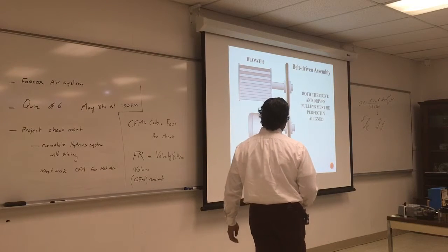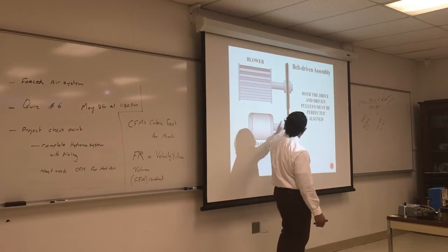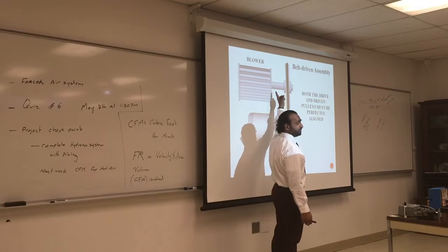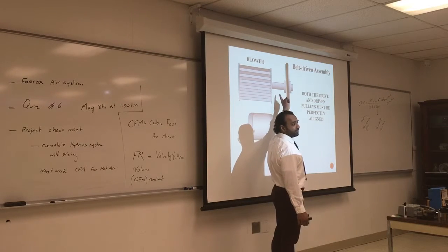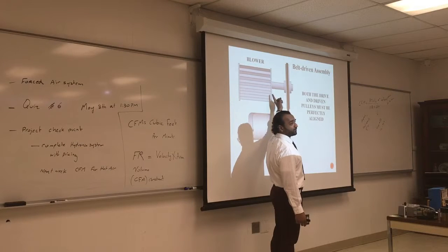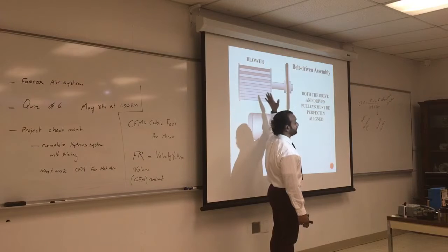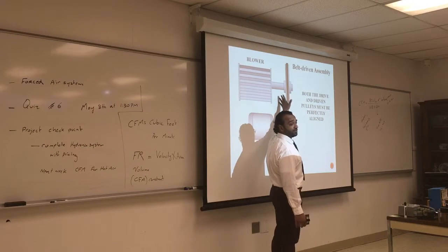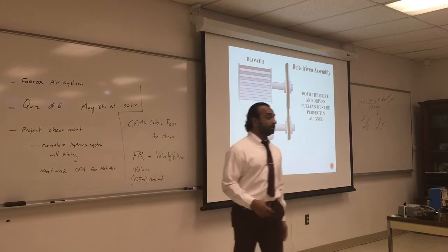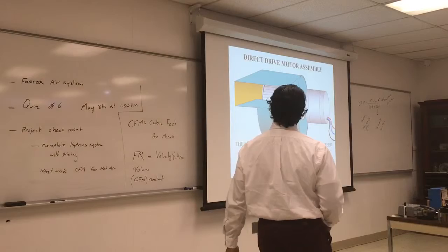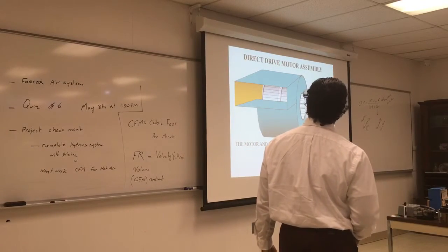So this is the blower motor, this is the belt drive. We have the motor with the pulley and the belt. This pulley will hardly ever break. All you have here is bearing and pulley. Sometimes you might have to clean it, but you don't have to take it out. Taking the squirrel cage out of the duct is a very big job. That's why they put the motor outside and use a belt drive to turn the fan. The assembly.